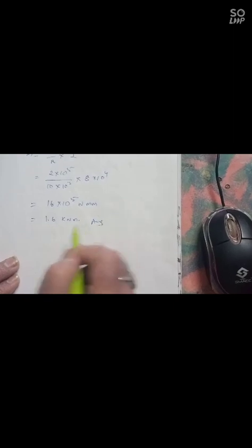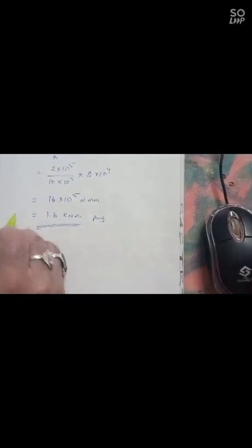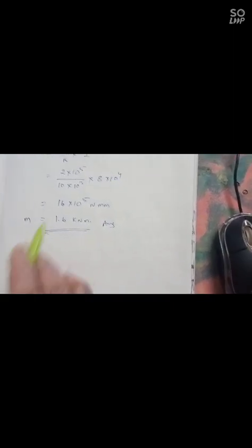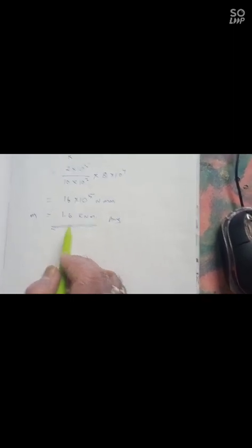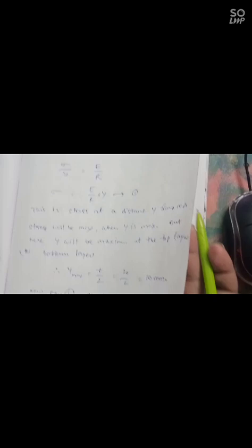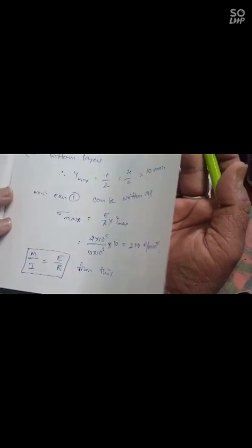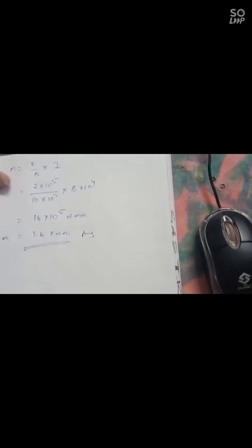So this is the answer, the maximum bending moment occurred. Maximum bending moment is 1.6 kilonewton meter, and the maximum stress is 200 newtons per mm square.